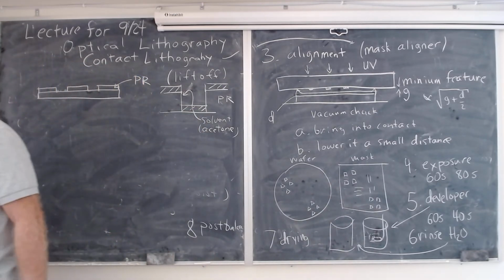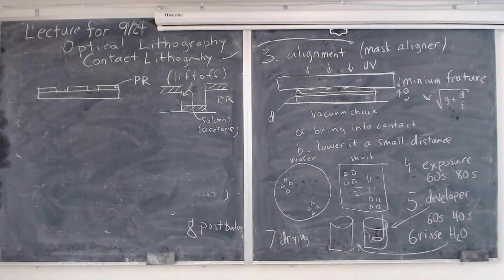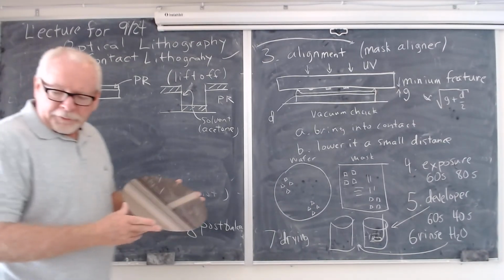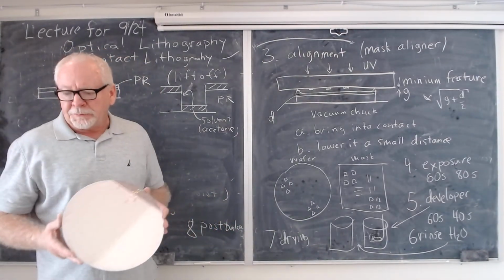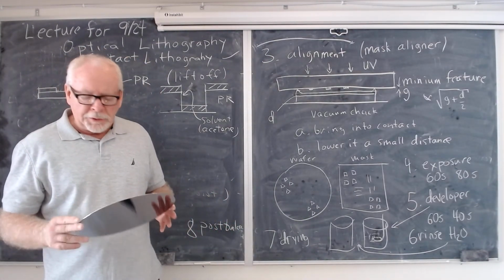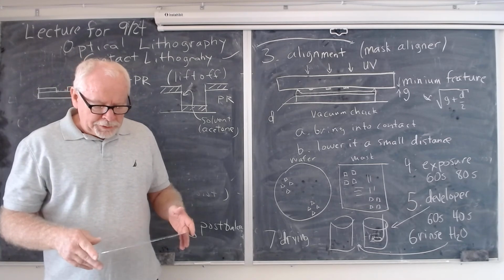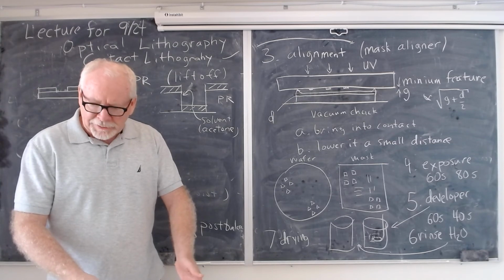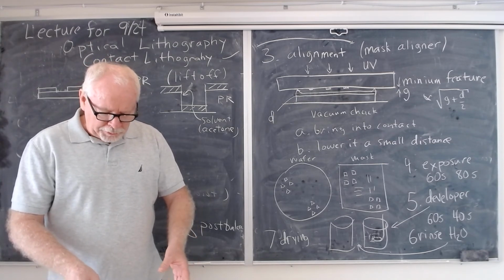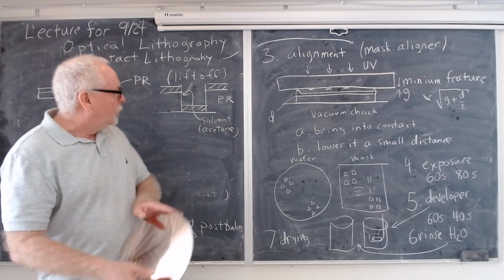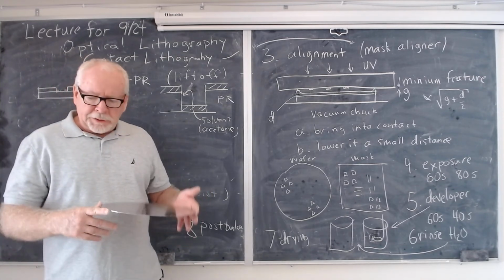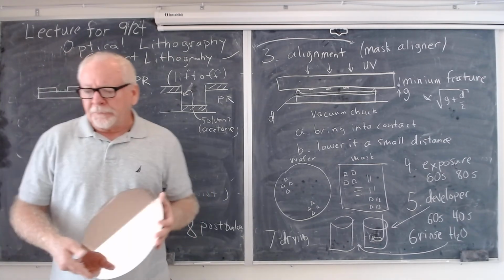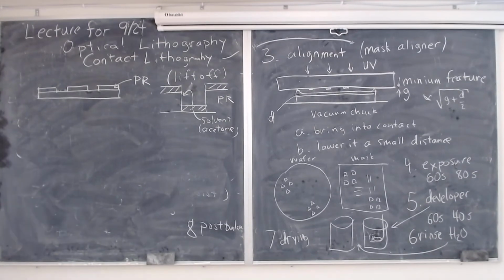And the lift-off process. Now, you could never do lift-off on this, and so lift-off tends to be used more for research-grade devices or smaller devices. Because if you think about it, you're asking to put this in an acetone beaker, and over the entire wafer, you want that to be happening. See, I should have brought a smaller wafer, like a 3-inch wafer. This is a 12-inch wafer.